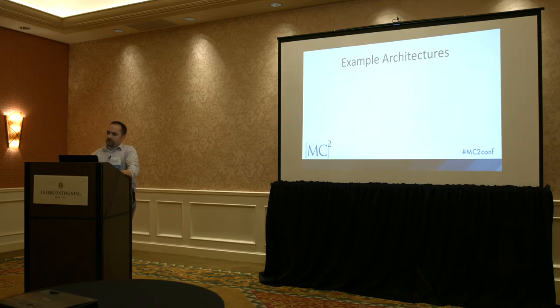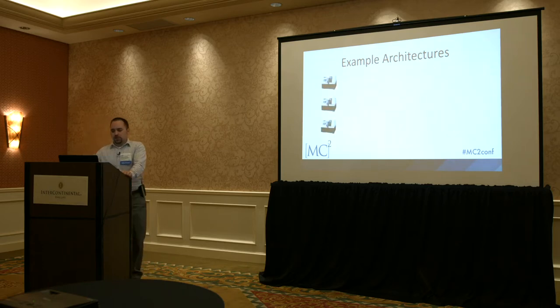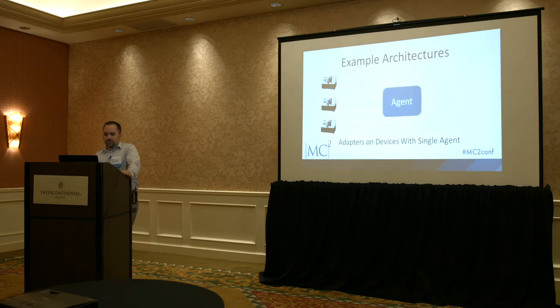So let's say we don't want to run the agents on the machine tools themselves. That's also an option. So maybe let's have the adapters on the devices, and we'll pipe all the content into a single agent. You could also pipe the content into separate agents that are running on separate servers, virtual machines, Raspberry Pis. It doesn't really matter, as long as it's something that has enough strength to run an agent. In this case, the adapters are still on the devices. The agent is configured to look to those devices for adapters, and then the client connects to the agent, and we have a successful architecture.